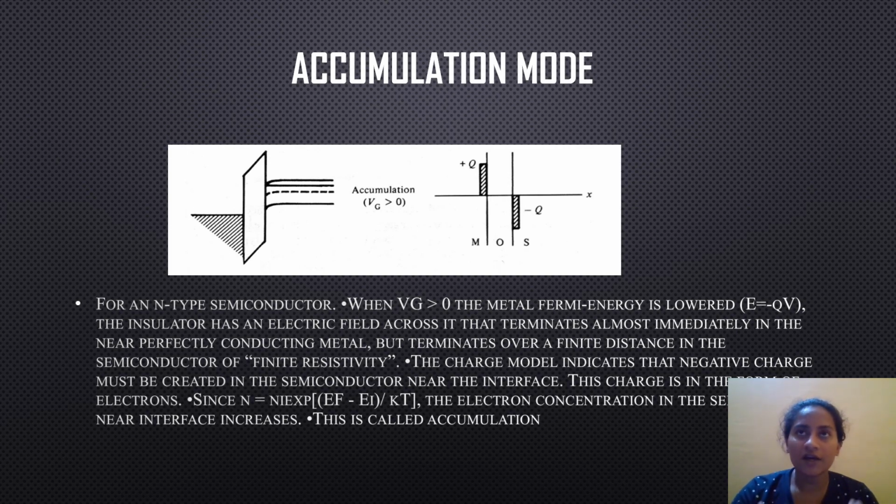Whenever the depletion region is less, the current will flow inside the material. Whenever the depletion region is increasing, the flow of electrons from the n-type substrate to the p-type substrate is not possible. It doesn't allow the electrons to accumulate over the holes. Why? Because the depletion region is very wide, and at that time the current does not flow. Because it is in the reverse biased condition.